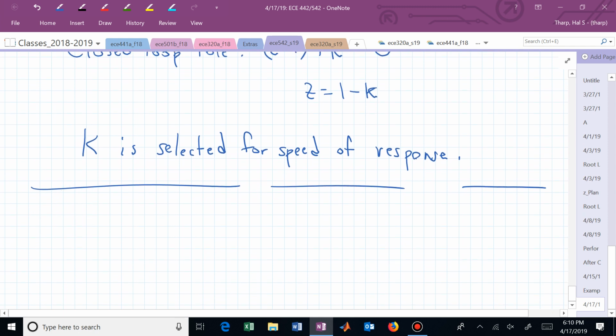Suppose somebody said, well, is this controller very robust? Have we talked about robustness or what that even means? Is your controller going to still be effective if your plant is not really where you thought it was? Here we thought our plant had a pole at 3/4. Maybe you did a poor job of modeling your plant, and maybe your plant pole was actually somewhere other than 3/4.